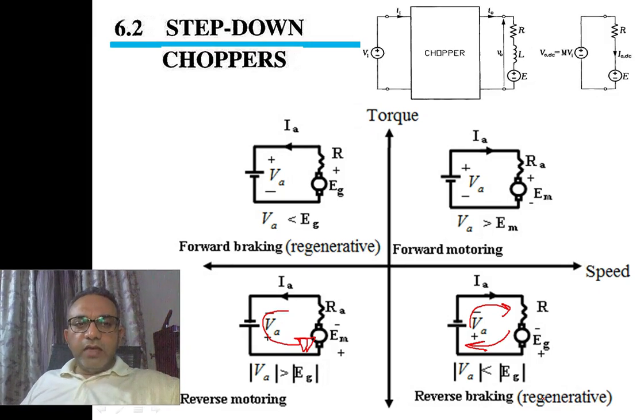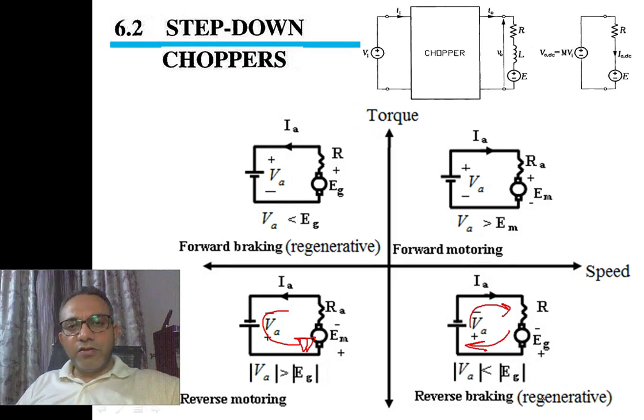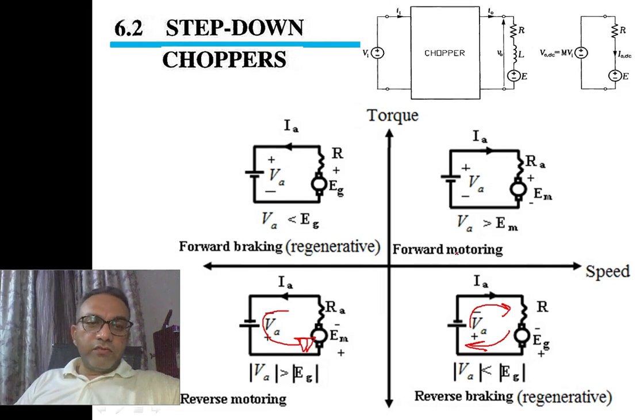Now, if we stop here for a while and think, sometimes we are supplying energy from the source to the motor, and sometimes we are returning energy from the load to the source. This cannot be achieved while working only in the first quadrant, nor can the motor running in both clockwise and counterclockwise directions.